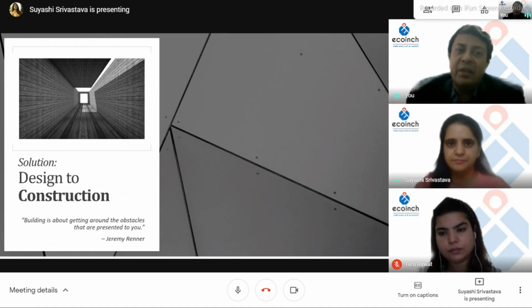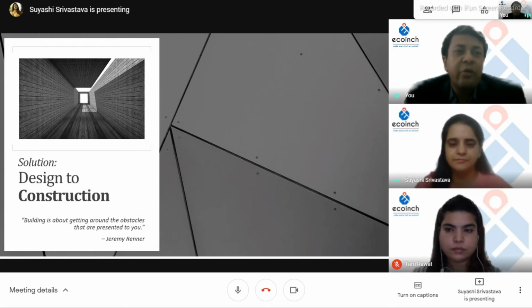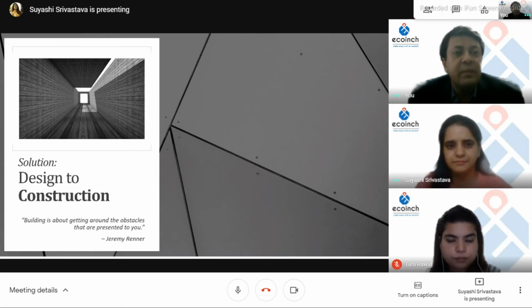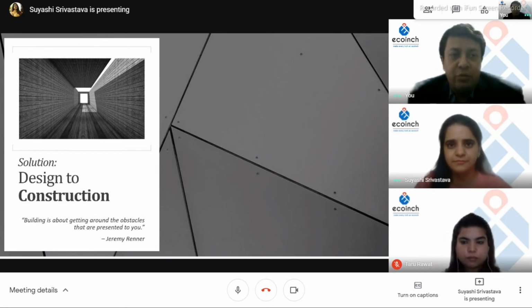Once we have done this lab vetting of the entire design, we then produce the technical drawings, which are called the construction drawings. Those technical drawings are what are used on the site, and they're called good for construction drawings. These construction drawings also typically have 3D elements from our design to aid the construction worker in developing and delivering the product as it was intended to be.